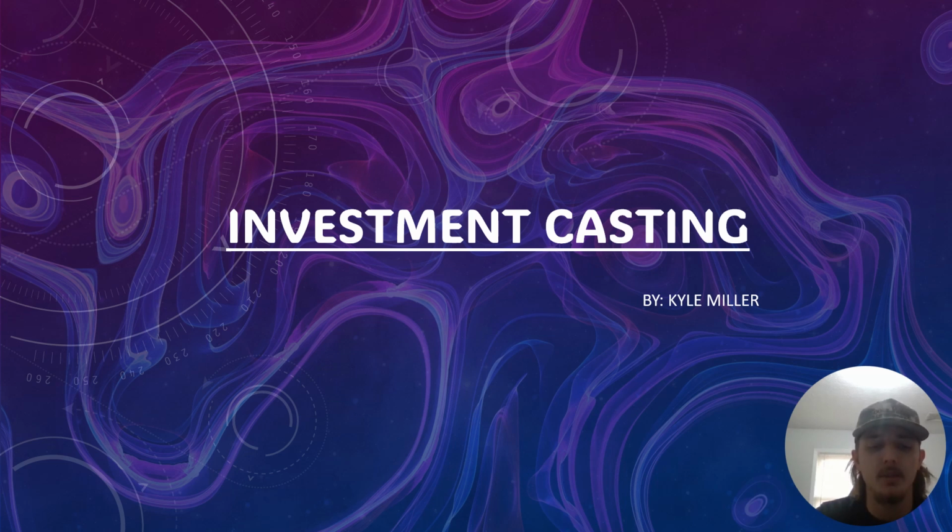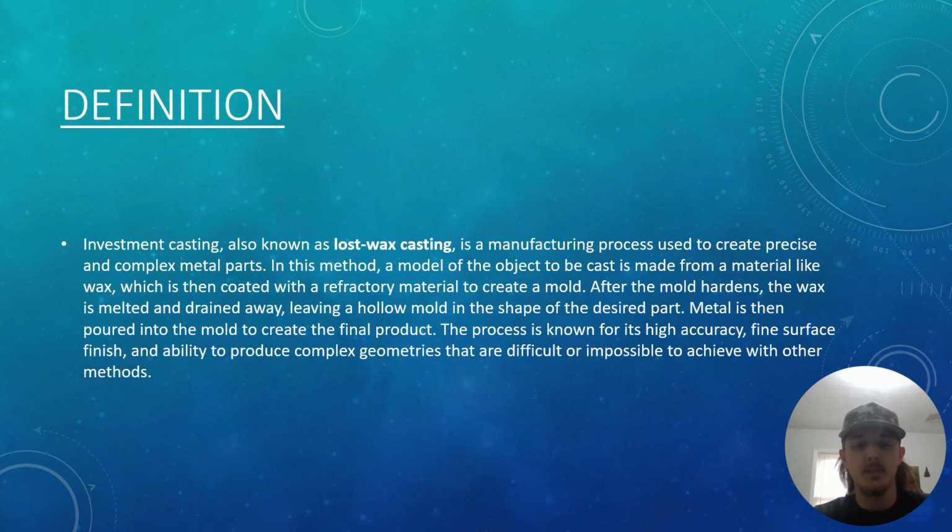Today I'm going to be talking about investment casting. So investment casting, also known as lost wax casting, is a manufacturing process used to create complex metal parts. In this method, a model of the object to be casted, made from a material like wax, is then coated with a refractory material to create a mold. After the mold hardens, the wax is melted and drained away, leaving a hollow mold in the shape of the desired part. Metal is then poured into the mold to create the final product. This process is known for its high accuracy, fine surface finishes, and the ability to produce complex geometries that are difficult or impossible to achieve with other methods.